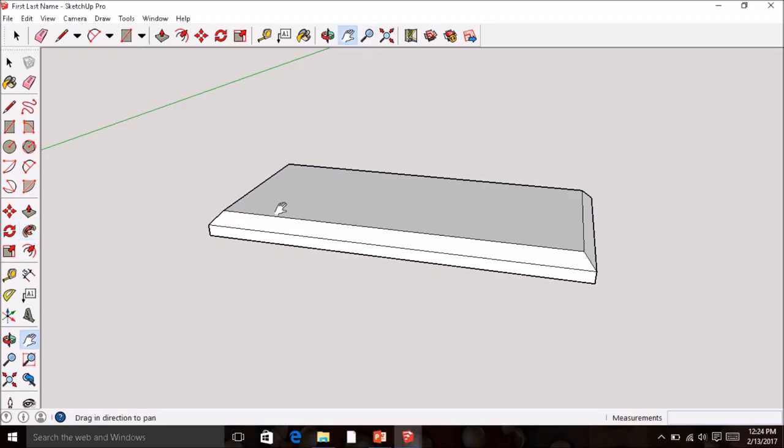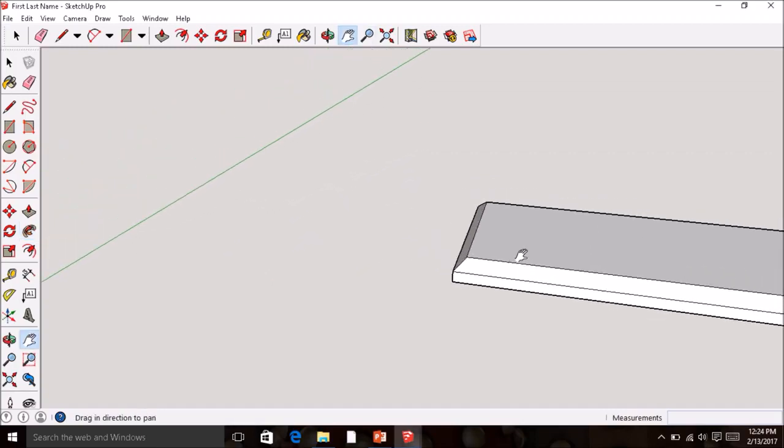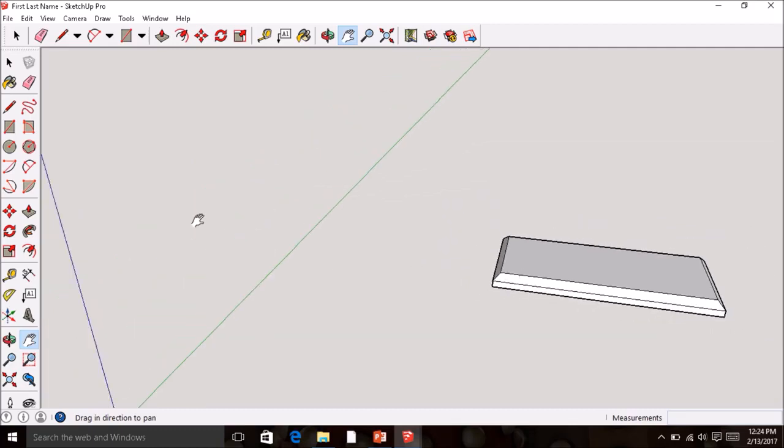But I'm going to start by moving my base a little bit over, and I'm going to come over to this left side, and I'm going to draw my clock faces. To do this, I'm going to grab the rectangle command, and I'm going to come down here and click once over by this green line, and move it back into the right, and I'm going to type in 5.5, comma, 3/4, and hit enter, and it's going to make a rectangle.